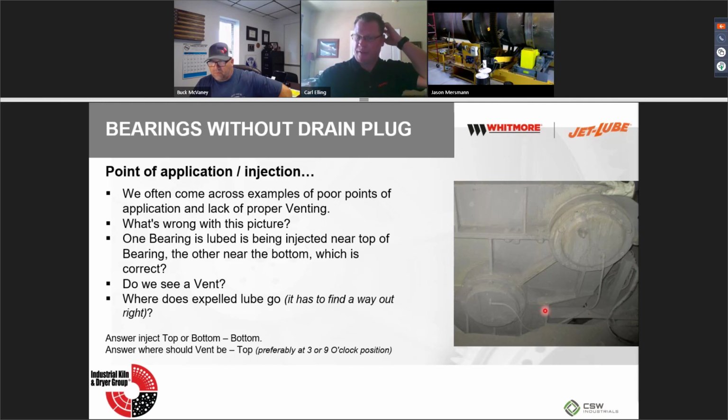So I'm going to poke your memory on this one. If you remember going back, we were discussing the hydrodynamic boundary lubrication, where the shaft is rotating in this direction right here, and the shaft over here most likely is rotating. You wanted the lube point on the bottom, because this is where most of your boundary lubrication is, where the journal's rotating. So just to give you a heads up, if you apply that lubricant here, you're getting fresh stuff right before this lubrication point where you need it the most. So correct answer is at the bottom.